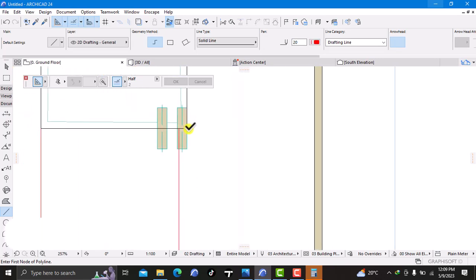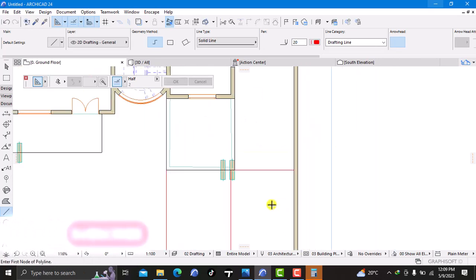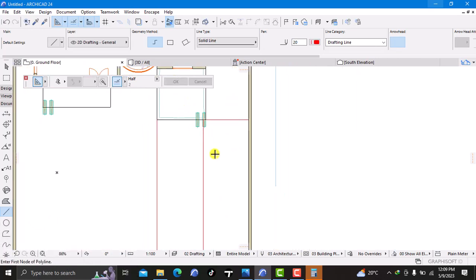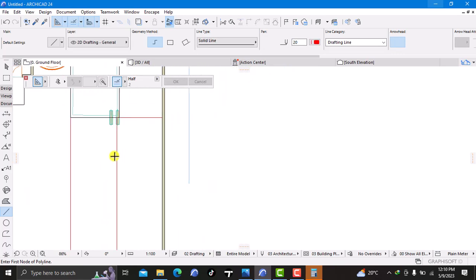And then from this point I'll just drag another line to that end. So then I want to do a distance that will allow me to park around 3 cars over here. So from here I'll do a distance of, let's say, 9,000.